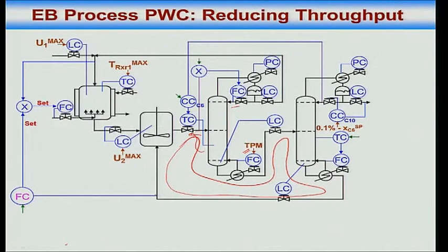When I maintain this flow by changing ethylene, it takes a long time for its effect to come in the DEB. When I change ethylene, its effect will be after a long time, right? When I was doing this, its effect was immediate, right? So I have made a compromise. What is the compromise?